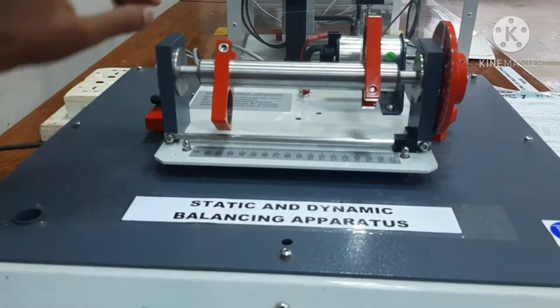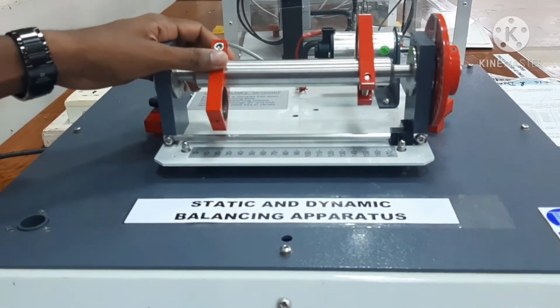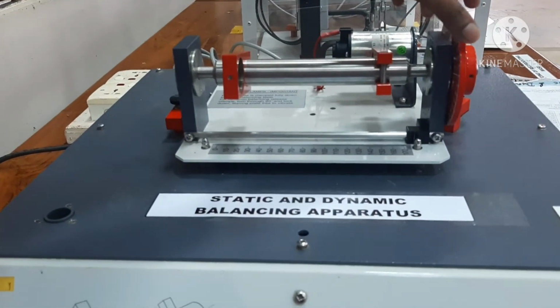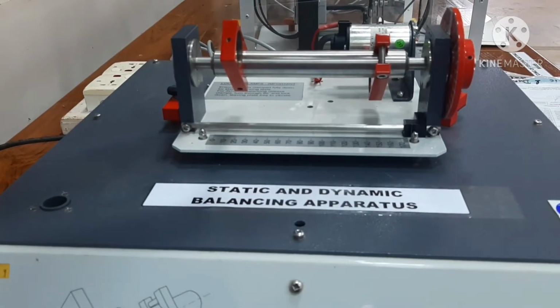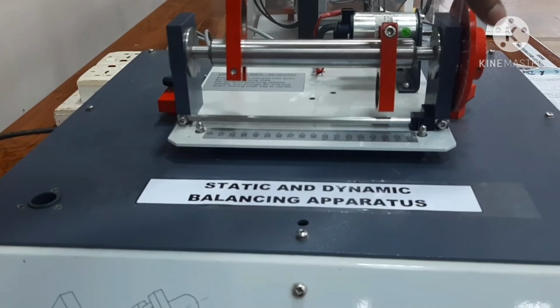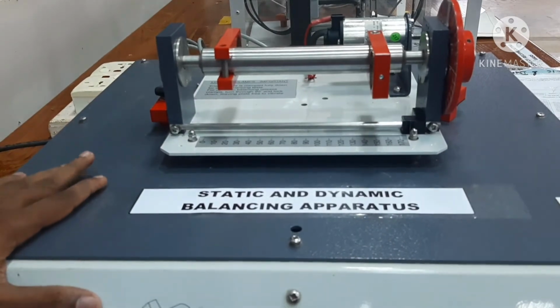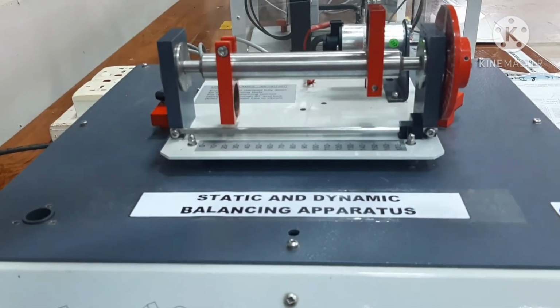How can we check whether this is statically balanced or not? For that we have to rotate it to some angle and see whether it remains in the same position or changes position. It remains in the same position. Therefore it is statically balanced.